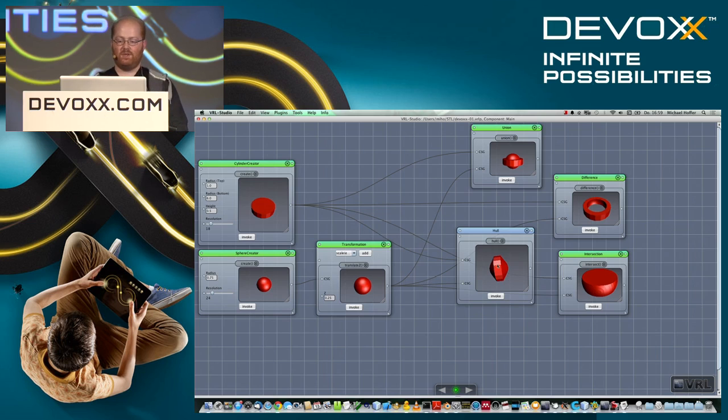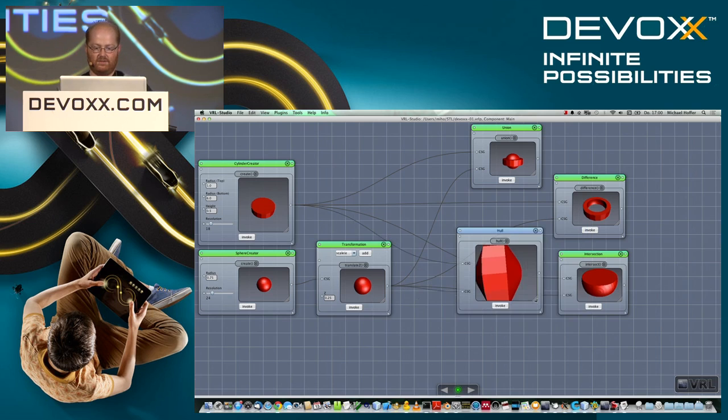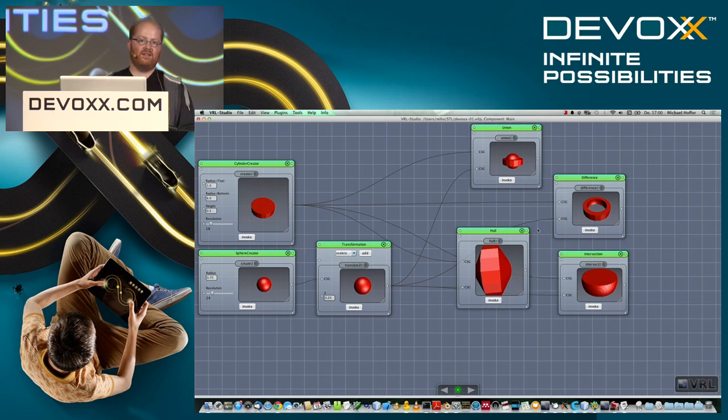In many cases it works, but it depends on how the heat bed works, and also the resolution of the object, because if they are too small here, you won't be able to print that without support, because it will just roll out of the printer. So you really have to think about how you design the objects.